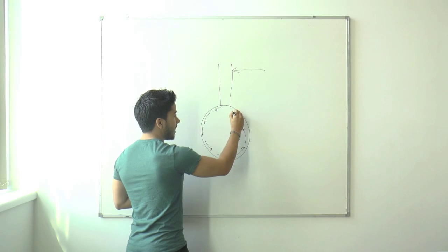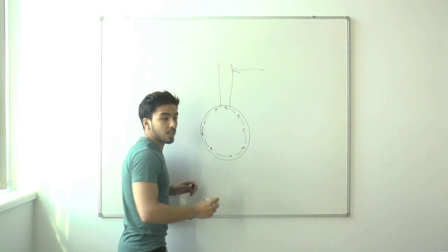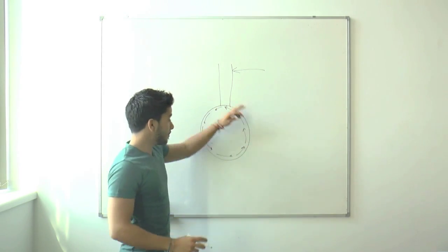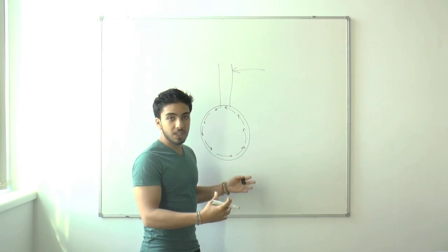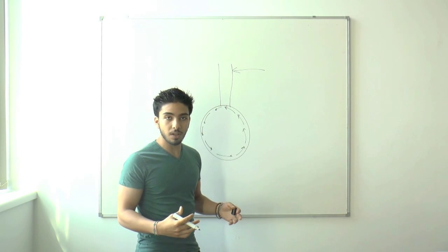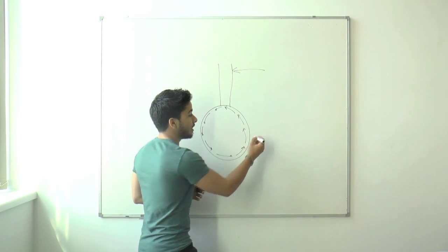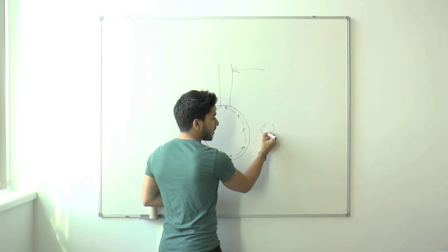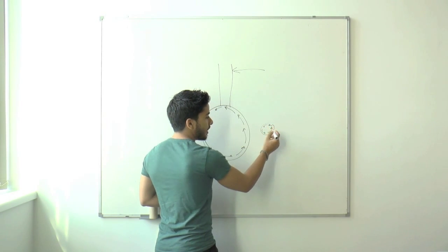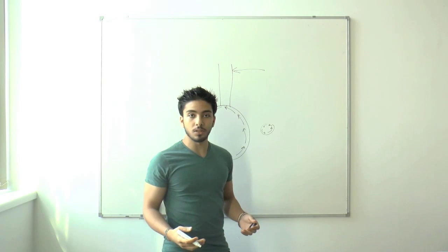And that is how torsion is resisted in shear. And the wider this loop, the bigger this loop, the more material there is to resist this torsion. Now, what would happen if we had a much smaller cross section? Then there would be less material to resist it, and it would have less resistance towards the torsion.